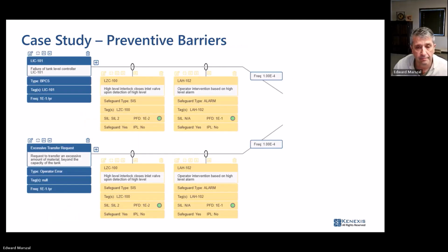The mathematics here is fine, but as we evaluate the probability of failure on demand of a safeguard on a yearly probability of failure, aren't we penalizing ourselves when we show the same safeguard with the PFD more than once? Eventually, if that level alarm were shown with 10 different initial causes, it wouldn't do anything anymore. Well, that is an excellent question.